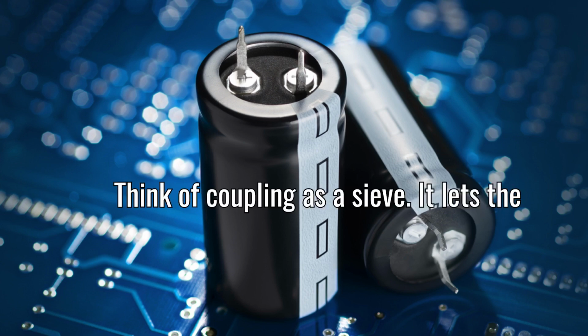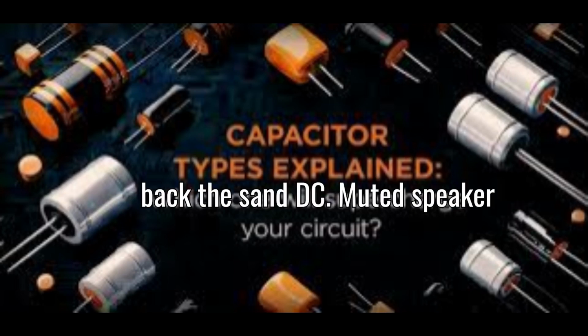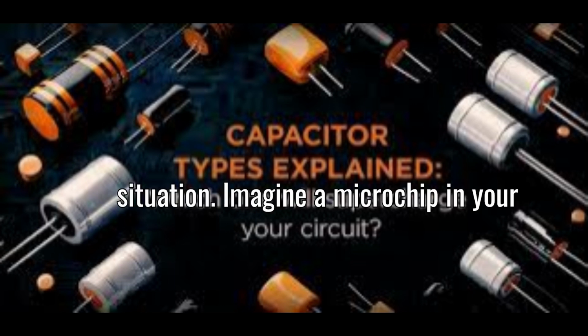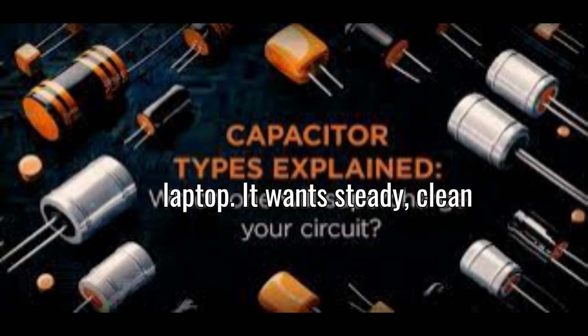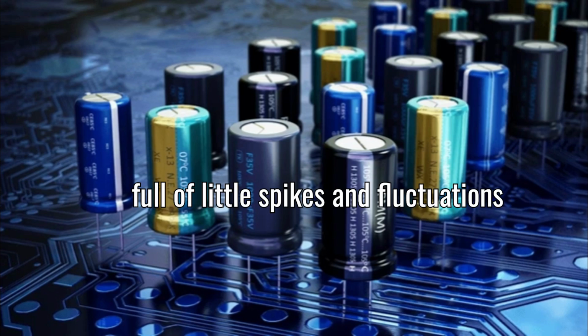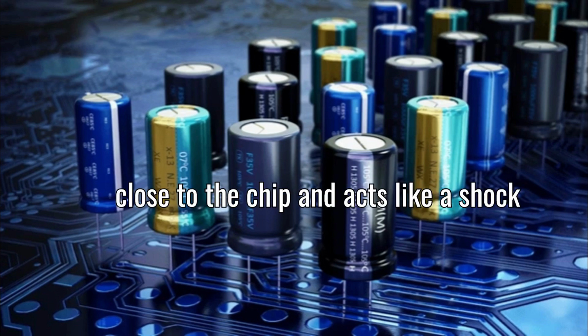Analogy. Think of coupling as a sieve. It lets the useful water signal through while holding back the sand, DC. Decoupling, noise reduction. Now flip the situation. Imagine a microchip in your laptop. It wants steady, clean power. But power lines are noisy, full of little spikes and fluctuations caused by other parts of the circuit switching on and off. A capacitor sits close to the chip and acts like a shock absorber.